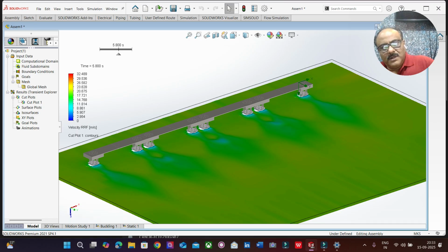Now the impact of the vibrations on that bridge deck, because of the vehicles or the moving loads or influential loads or rolling loads, is going to impart some load on the substructure. From the substructure, it goes to the pile, and then from the pile to the riverbed.